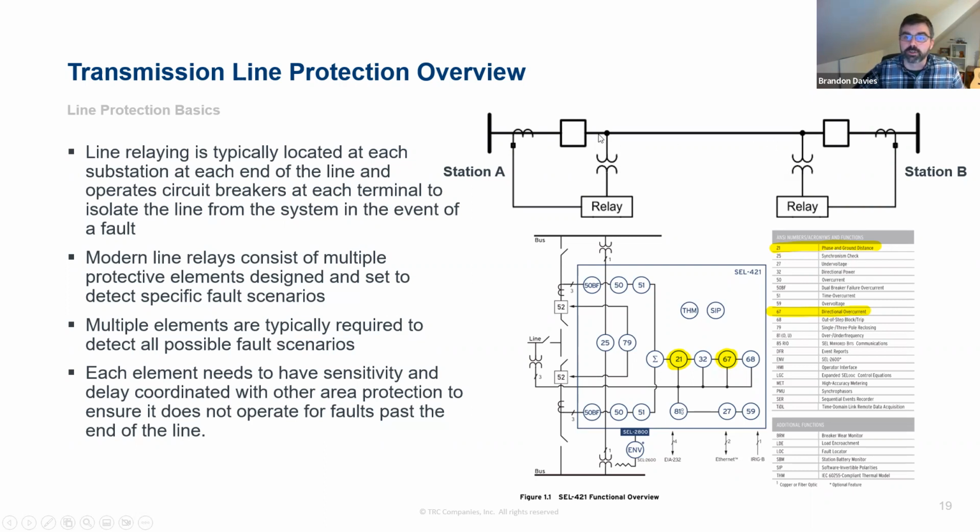And if you took this line out of service and grounded out the three-phase conductors here, because you had people doing work on the line, that would be typical safety procedure: you'd isolate it through a switch or an open disconnect. You'd open your breakers and you'd apply grounds to both ends of the line to provide safety for the workers that are going up there and replacing insulators or doing things like that. So, Paul's question: what happens if you then forget to take the grounds off and close a breaker to try to energize the line?